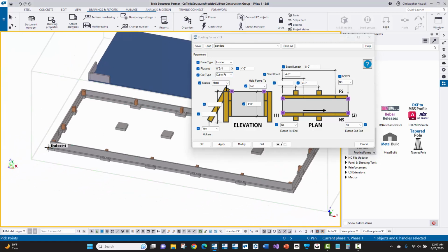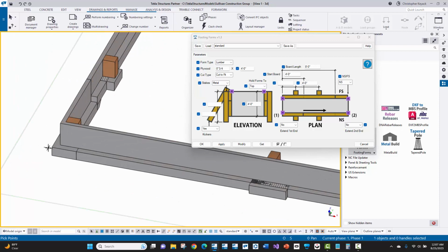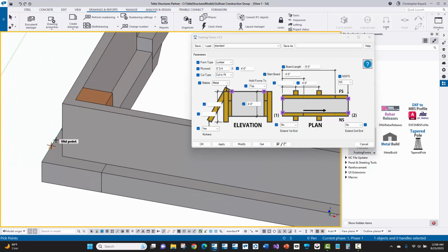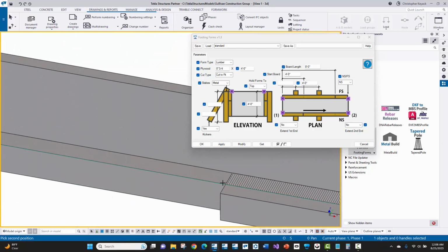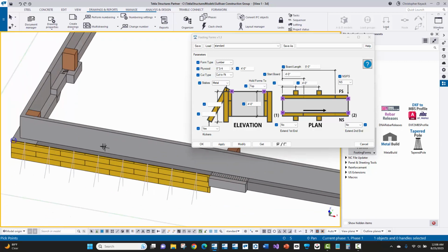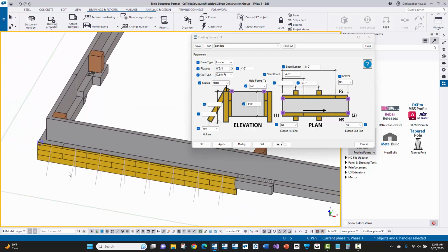wood formwork. Now, you'll see here that there is a concrete massing model, and this can be a native Tekla Structures model, or it can be an IFC file or reference model that's been brought into Tekla Structures. Now, what we'll do is we're going to pick at the top of the concrete here, and I will just go ahead and span across by picking these 2 points. And then what we'll see here is within a few seconds, we'll see that the wood formwork has been then